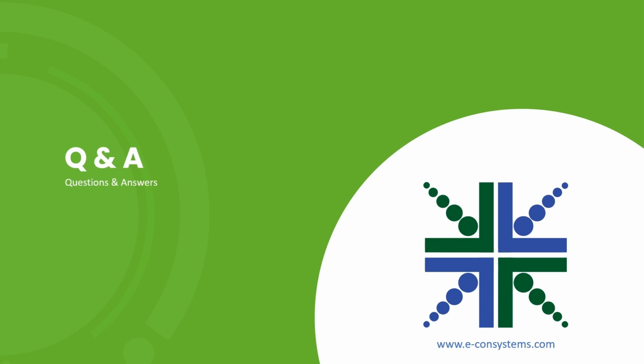Right. So the next question is, what is the difference between WDR and HDR? Based on my experience, WDR is better as it is hardware based. Am I correct? So the question is, ideally, what is the difference between wide dynamic range and high dynamic range? In often confusing terms, somewhere we use WDR, somewhere we use HDR, but generally, since the early days of mobile phones, HDR is a technology used, and most of that HDR runs on the software.